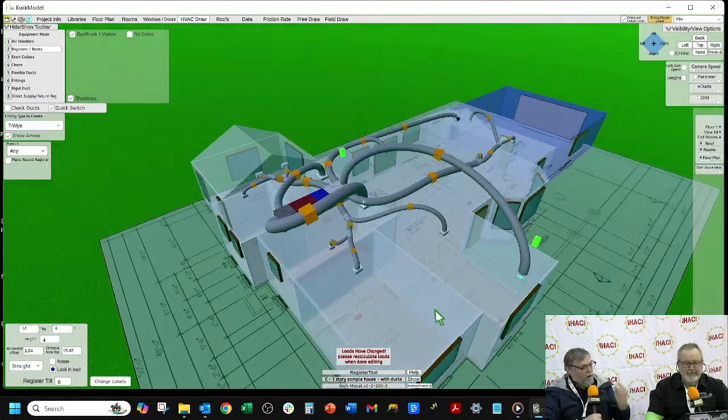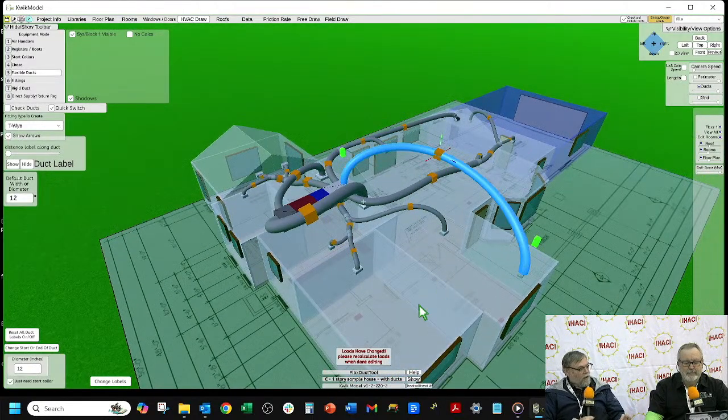So do you prefer ducts in inside walls as opposed to outside walls? I do. My philosophy is throw the air the opposite direction that it wants to go. As the air is coming into the room, it wants to push that air out of the room. So my theory is put the register close to the door, blowing against that air, and you get better mixing that way. Right, you get better mixing in the room. You have to pay attention to throw and things like that to make sure the air reaches the far wall. But if you put it on the exterior wall, it just kind of goes with the flow, and there's not as much mixing. The air doesn't spend as much time in the room that way.